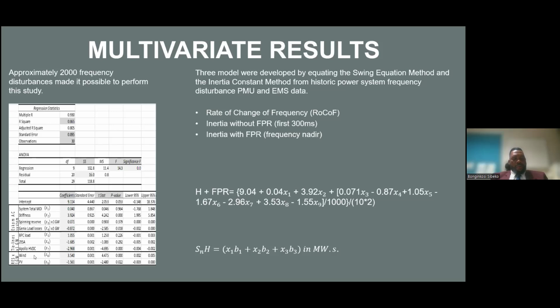At that time we took the spinning reserves, and also what we call the load losses or partials, units that are not capable of doing full load. Then we took the tie line flows to estimate how many of the neighboring countries' units are synchronized. Then we also added wind and PV. These are just variables for what was happening during the disturbance at that time.